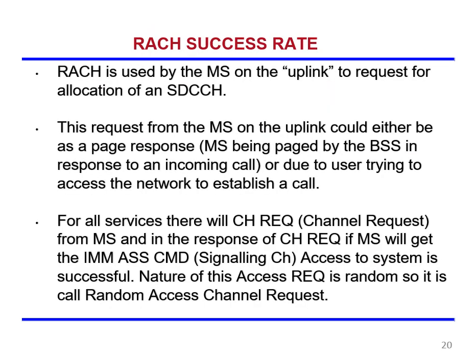RACH success rate. What is this RACH? Random access channel. So random access channel success rate should always be as high as possible. If the success rate is poor or RACH congestion is more, it is a problem. So what is RACH and what is the purpose of RACH? RACH stands for random access channel. It is used by the mobile phone in the uplink direction, whenever you want to make a channel request.